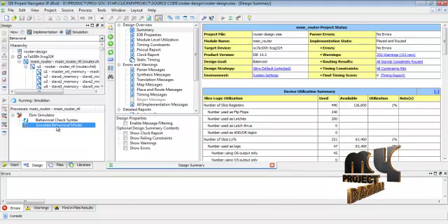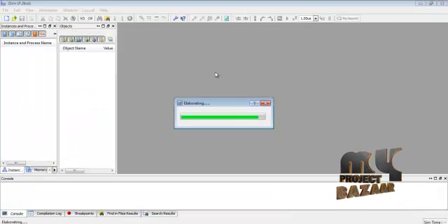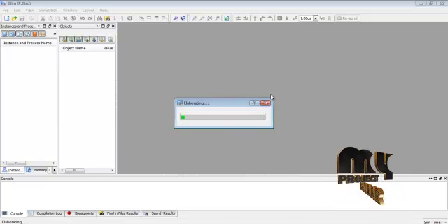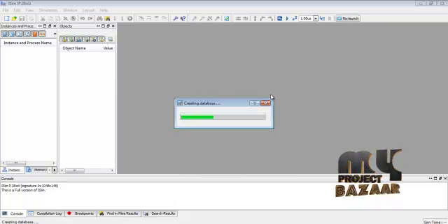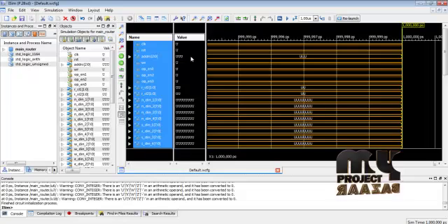Then create the Xilinx ISim project. This ISim project is mainly used to simulate our overall NOC design. We just apply the binary input data for the forecast NOC input and get the output for the star based NOC architecture designs based on our selection line. This is the simulation process.